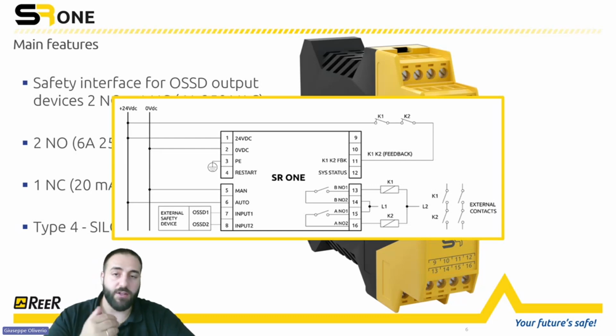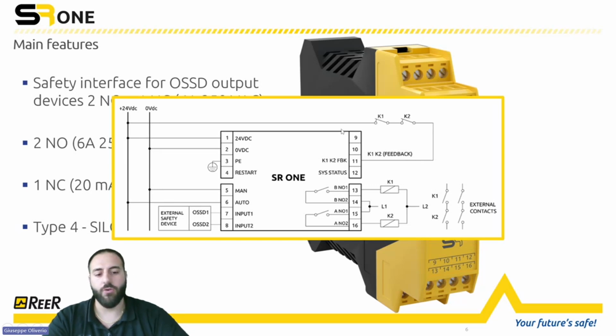And for the manual reset, the reset button would be connected to pin number 4. Like other interfaces that we have in our portfolio, we can connect the normally closed contacts, so the feedback contacts, directly to pin 11. So the module itself is in charge of checking the feedback contacts and the switching of these feedback contacts based on the inputs and based on the time. Here on pin 7 and 8, you can see the OSSD inputs.